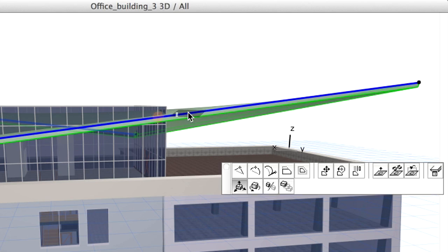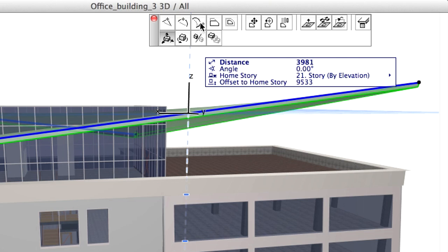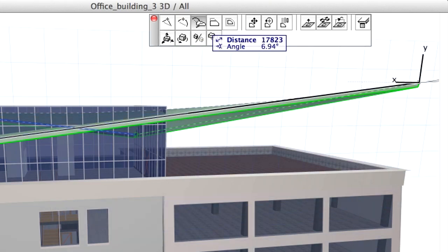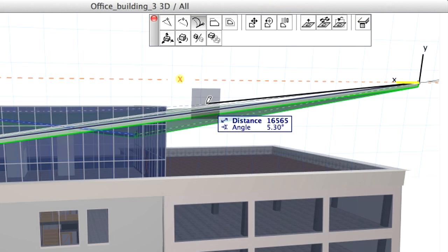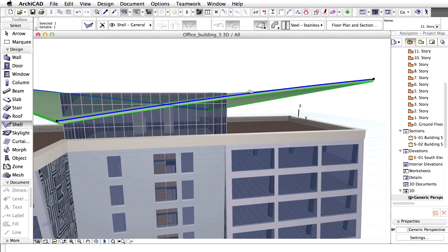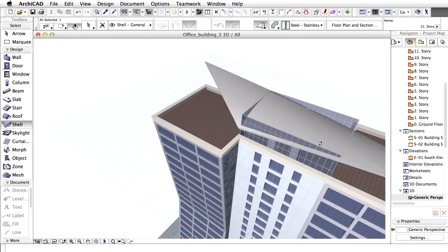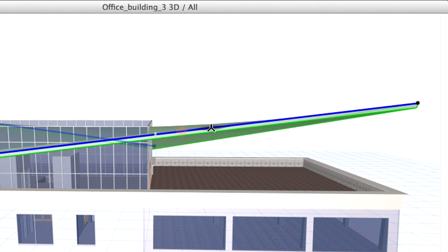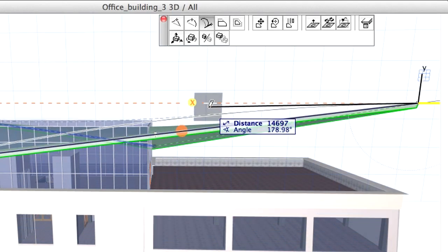We would like to curve our shell profile slightly. Click on the profile edge and select the Edit Segment Using Tangent option from the pet palette. Move the cursor upwards and click when the arc is acceptable. Please try to keep the top of the surface of the curved shell element below the top of the curtain wall structure. Repeat this editing with both profiles.